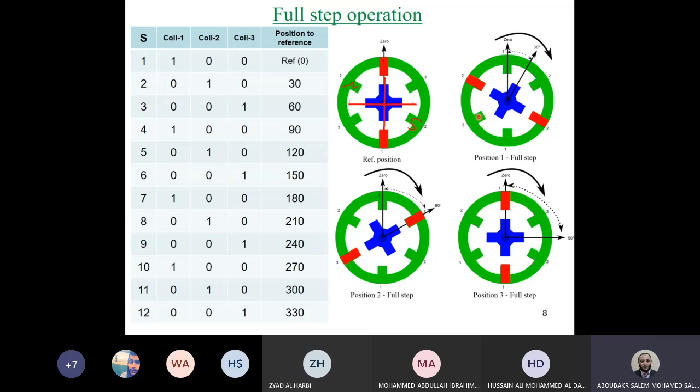And if we energize coil number 3, we will find that the flux will prefer to move through this tooth, and moving like that up till returning back to tooth number 3. Is it right? So if this is the case, the machine will move another 30 degrees and will be in that position. So here we have the new position, which is 60 degrees. So this is the pulse or the sequence and the position for step number 3.